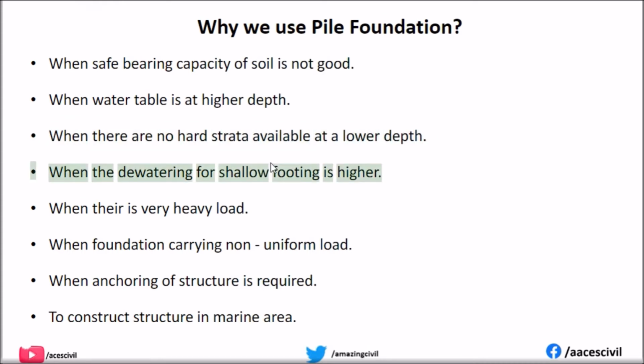When the dewatering for shallow footing is higher. When there is very heavy load. When foundation is carrying non-uniform load. When anchoring of structure is required. To construct structure in marine area.